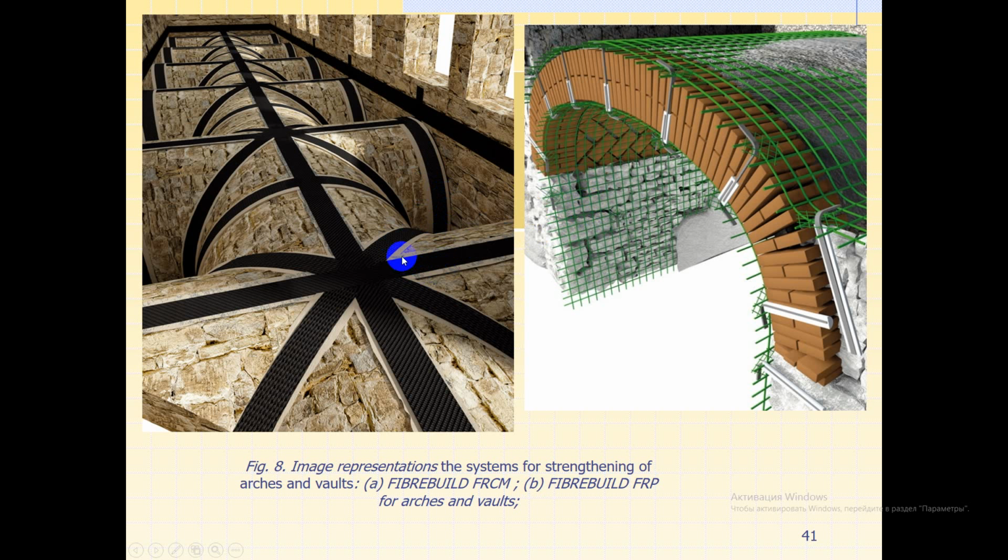The reinforced render with fiber-reinforced cementitious matrix, where glass fiber reinforced polymer meshes, connection and accessories are combined with preferably lime-based mortars to obtain a thin collaborating reinforcement capable of improving mechanical strength diffusely and homogeneously.